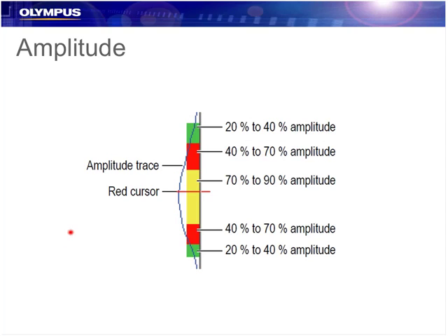Just a bigger trace of that. So it often looks compressed on the zone because we're looking at many zones close to each other. The A-scan can be hard to determine the height, so we use the colors instead. So here's the typical A-scan trace. We can see at the lower end of that A-scan, even though it doesn't look like it's 40%, we know up to this point everything is below 40. Then we reach 40 to 70 in the red, and here we're 70 to 90, and then as it drops back off, we're green again. So we quickly can look at the colors and make our distinction of what needs to be reviewed.